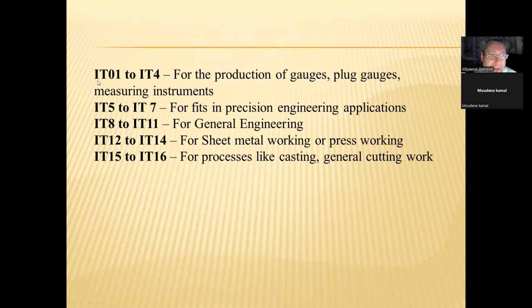We use IT grades from 01 to 4 for the production of gauges, plug gauges, and measuring instruments. From IT 5 to IT 7 for fits in precision engineering applications. From IT grade 8 to IT grade 11 for general engineering.